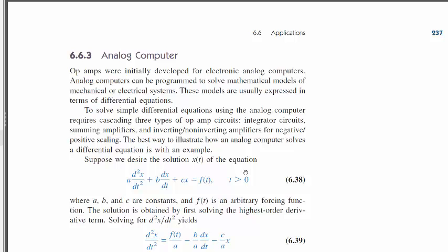We apply integration and gain to it, and that pulse of current gets converted into a voltage, and then my analog to digital converter can work with it. So that's one example. It's actually a really common example of what an integrating circuit is often used for, taking a very short pulse and making it something that's usable for the user. Okay, that's all.